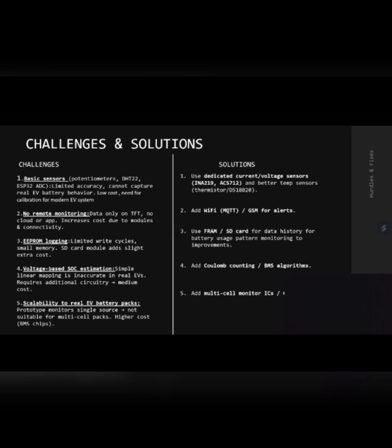Then no remote monitoring, data only on TFT and no cloud app is given. Then EEPROM logging has limited write cycles and small memory; an SD card module adds slight extra cost. Then voltage-based SOC estimation uses linear mapping and is inaccurate in real EVs, requires additional circuitry and medium cost. That is, basically the cost increases with certain circuitry.